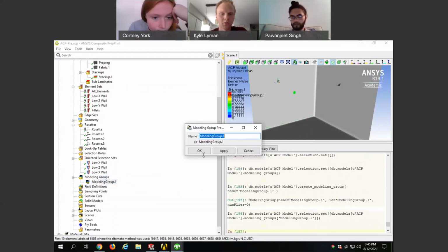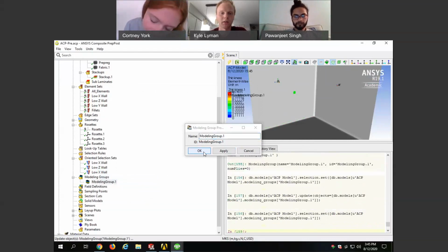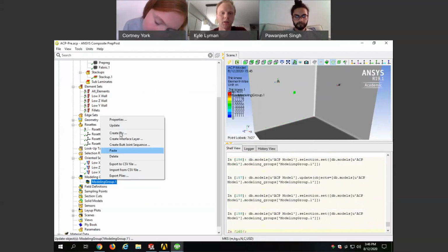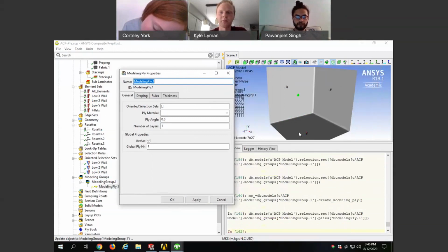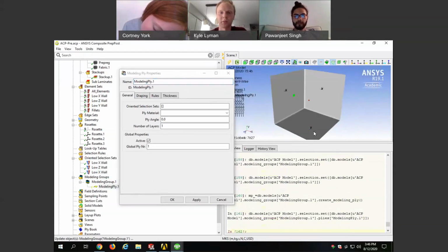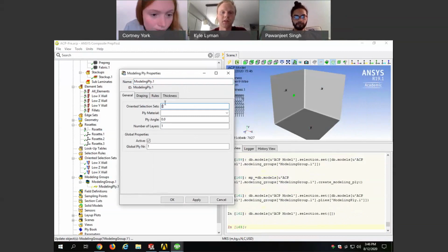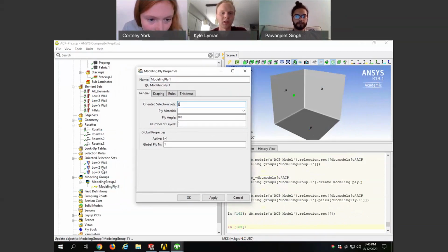Modeling group. You need to create a modeling group. Hit apply. Then we're gonna hit create ply right here. Right click on it. So we're creating plies, which is just another step in the process. We're gonna have to select an oriented selection set.